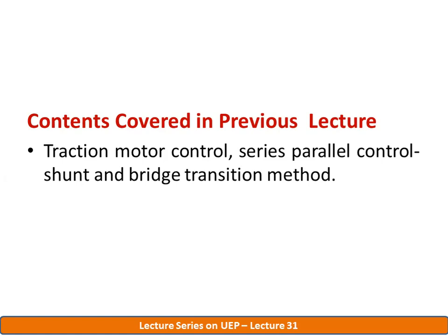In order to achieve high speed, the two motors are connected in parallel. When two motors are connected in parallel, the current is divided into two parts. In the previous case, in series condition, only I flows through the circuit, now 2I. Again, the resistance is inserted and supply is applied through the resistor. When the motor reaches its maximum speed, the motor speed can be controlled with the help of the field diverting method or any other method.